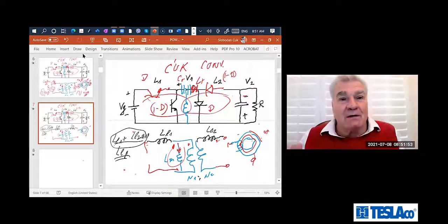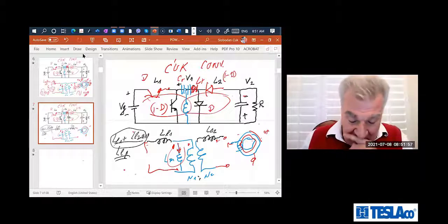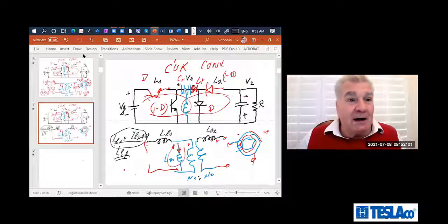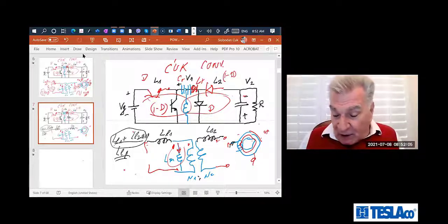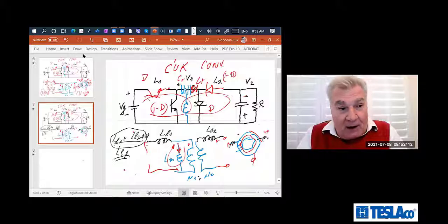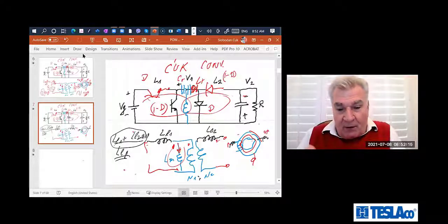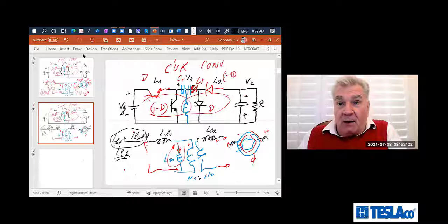And what is the practical aspect, regarding what you asked? The practical aspect is that the 60 hertz people didn't care that there was so much leakage on one side and so much leakage on the other side. Why? Because there is a common flux, but part of that flux is coupling from input to output, and also when you drive the secondary, part of the secondary drive is coupled to the primary.